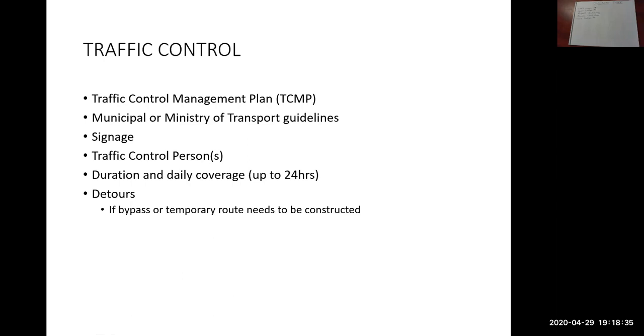I should mention, it's not listed on the PowerPoint slide here, that project specifications will typically advise you, the estimator, how many lanes you're allowed to close. Sometimes you're not allowed to close lanes, so maybe you need to build a detour. Sometimes you're allowed to close lanes not during rush hour, so during off hours. So maybe 9 a.m. till 3 p.m. you can have a lane closure. But for rush hour, you need to have all lanes open. So it's important to read the traffic specs when you're pricing your traffic management in your estimate.